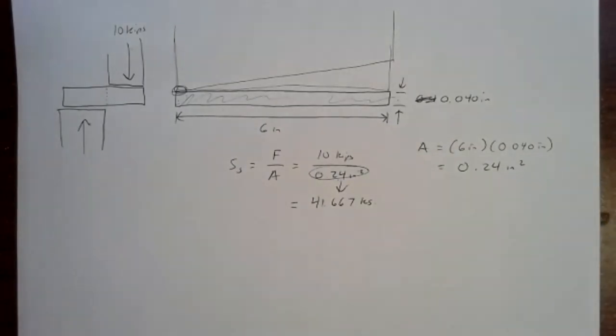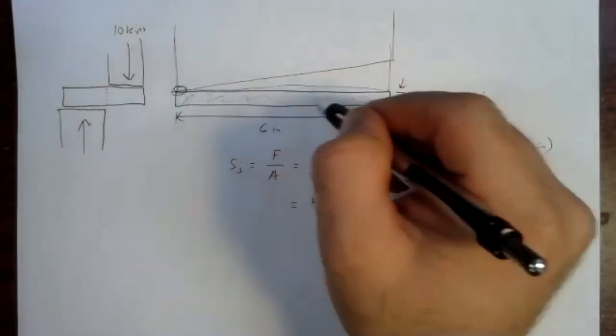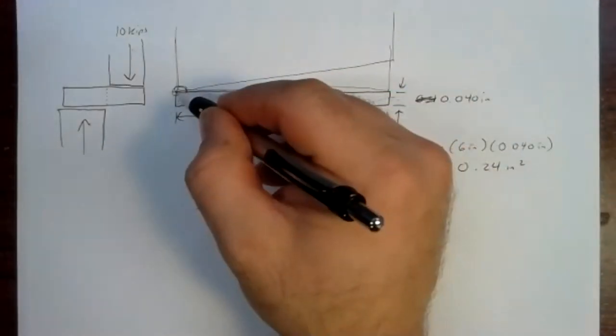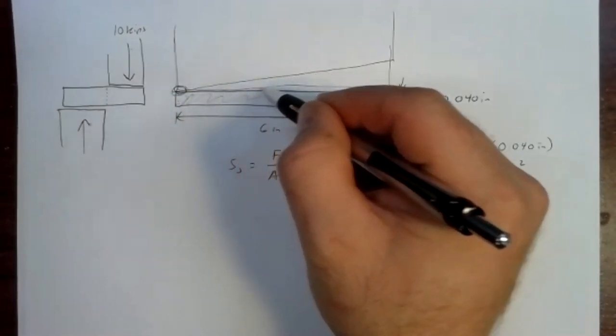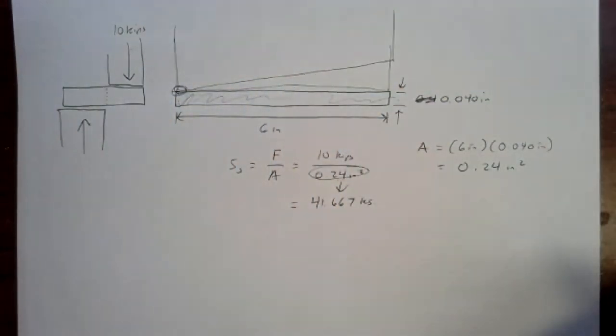This is why you can take even some relatively thick sheet metal, 63 thousandths, getting up into 10 gauge, things like that. You can cut through it reasonably easily on those sheet metal shears, as it's not trying to cut through the whole piece at once. It's just cutting through a little piece, and it gets that crack started and then just lets it ride across the whole part.